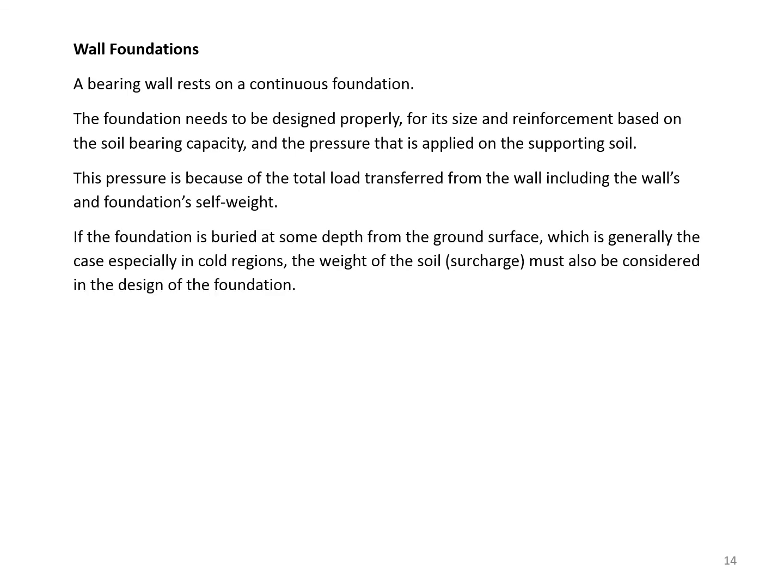If the foundation is buried at some depth from the ground surface, which is generally the case, especially in cold regions, the weight of the soil, which is called surcharge, must also be considered in the design of the foundation.